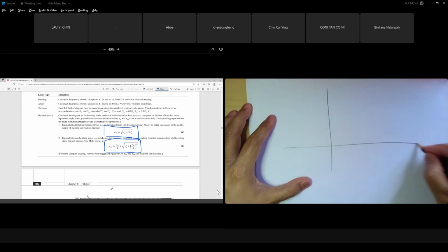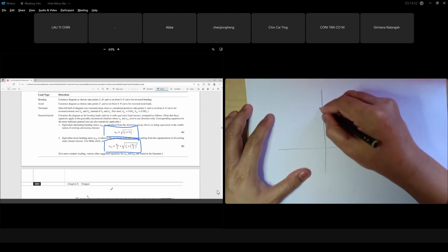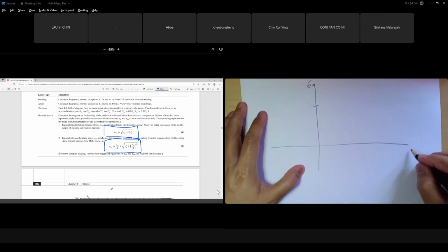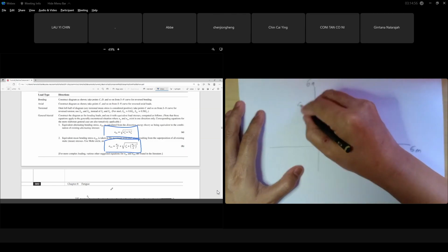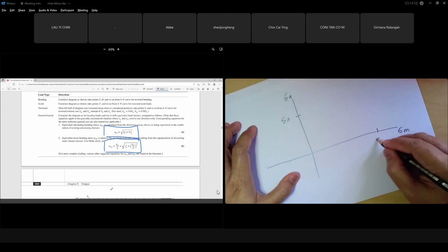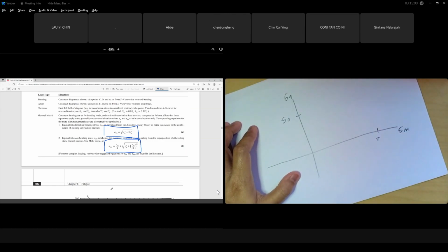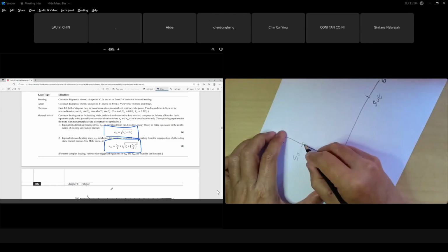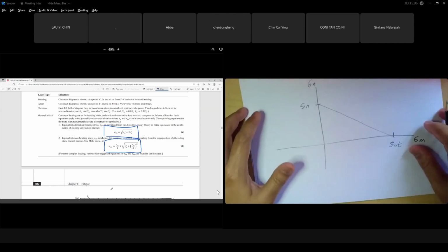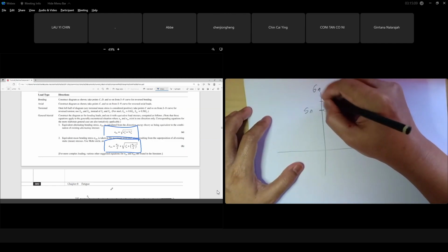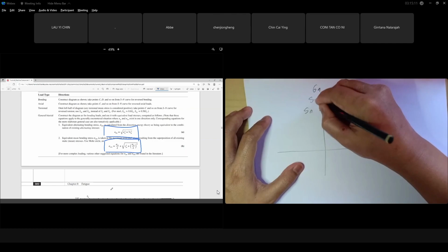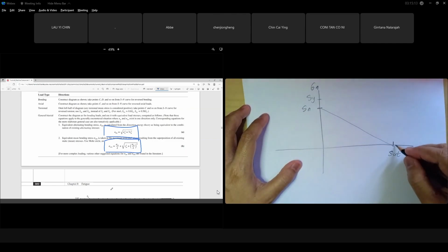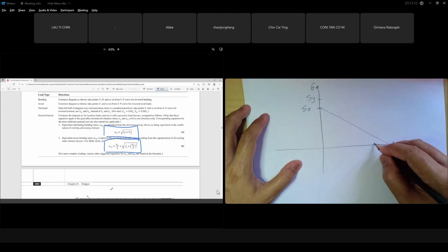But one thing before we quit one class, one more point of consideration, we have something called the yielding line. We have to look here. Say we plot this as our sigma amplitude and this is our sigma mean. This is our Sn, this is our SUT. Okay, this is our Goodman line. Remember, a little above Sn we have yielding. Remember, SUT is ultimate tensile strength, yielding is a little bit lower.